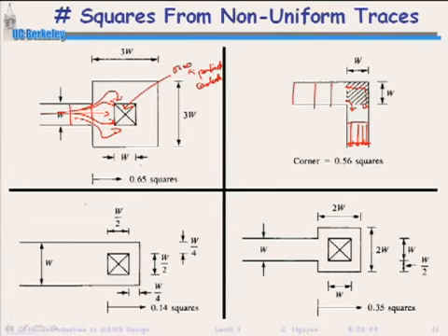So to work this problem, for example, at the top right corner, I would divide this into smaller squares, like that. Then I would say, okay, this current takes only one square path. This current here takes 3 squares, and so on and so forth, right? Each of these now represents a resistor, and you can sort of put resistors in parallel together. That's how you arrive at that 0.56, right? In the infinite, as these squares become infinitely small, you will arrive at 0.56 squares.